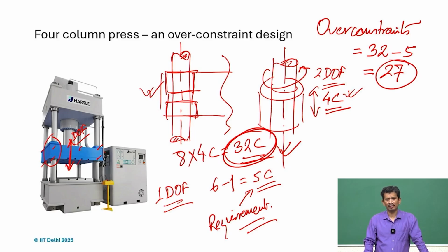we pay a very huge price, or the cost is so high if we go for higher precision, because then the tolerance has to be defined: the assembly, the parallelism, the straightness, the location of each and every hole we are defining for the bushings.